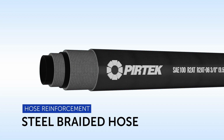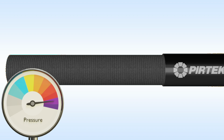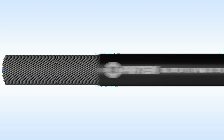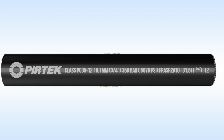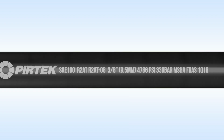The first hose shown is constructed using braids of high-tensile steel wire. The second shown is constructed using spirals of high-tensile steel wire. Hoses with braided reinforcing are used where there is a steady system pressure, and hoses that spiral are used where more flexibility is required or where the hose is subjected to high-pressure pulsations. The various types of outer cover are designed to protect the reinforcement from abrasion, ozone and weathering. The covering may also have fire resistance and anti-static properties, known as FRAS.